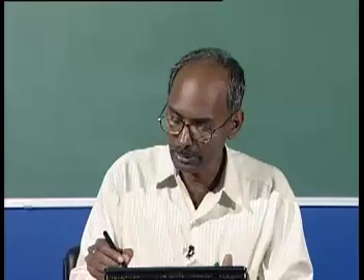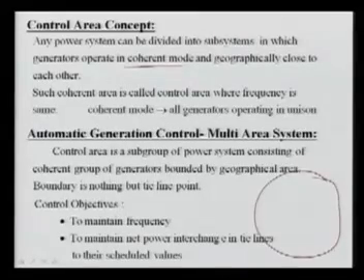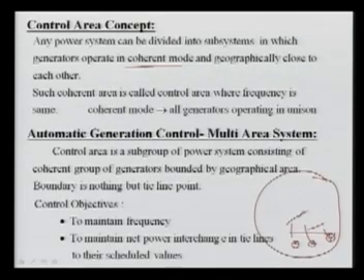For example, in a big power system, we have a few generators at these sites, and they are connected with some transmission lines, the network, and there is some change here in the loading. What will happen? Their angular separation will change because they have to supply more demand. It is not a steady state change because they will be oscillating.